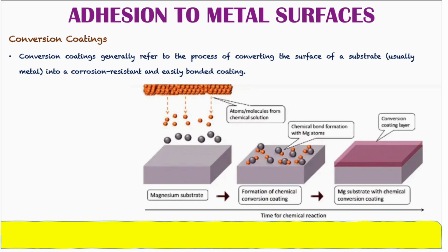Now, this conversion on the substrate occurs through a chemical reaction which results in the protective coating. The chemical conversion coatings basically become the backbone of many industrial processes, because these coatings are formed through a chemical reaction between the metal surface and the solution containing specific compounds. Now, the reaction produces a thin layer of adherent metal oxide or other compounds which enhances the properties of the metals. The coatings that work by changing the metal surface in this manner are usually the inorganic coatings.